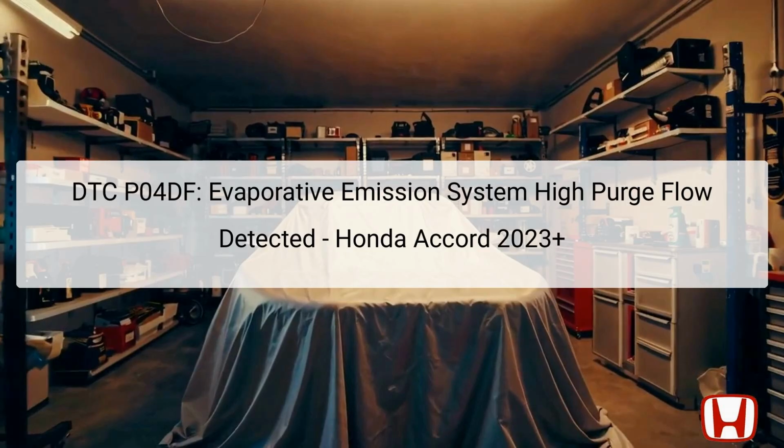If the FTP sensor fluctuates from negative pressure to atmospheric pressure while the engine is off, it triggers this diagnostic trouble code. The components involved include the EVAP canister purge valve, which opens to allow fuel vapors to be drawn into the engine for combustion, and the EVAP canister vent shut valve, which prevents outside air from entering the EVAP system. These components are strategically located in the vehicle's engine bay for effective monitoring and function.